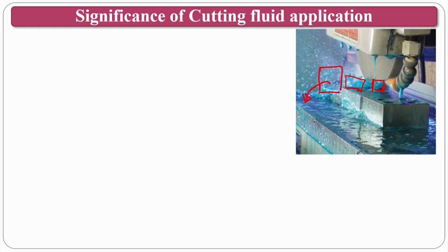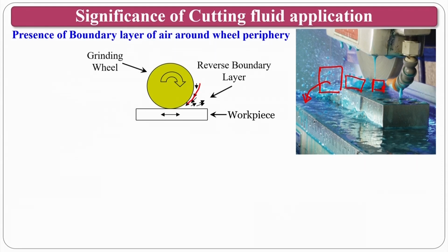Okay. So, you can supply the cutting fluid like this, or you can also supply the cutting fluid like this. You can supply from 0 degrees, or from a varying angle. You cannot go for 90 degrees or something, or you can, but it is not a feasible solution. If the grinding wheel is like that, you can send like this, or you can send up to 45 degrees, it may be very good, and beyond which there may be a problem. So, you should choose, and some of the people who want to take this up as research work, there are some papers, some theses, on optimization of the angle through which the cutting fluid should be sent.